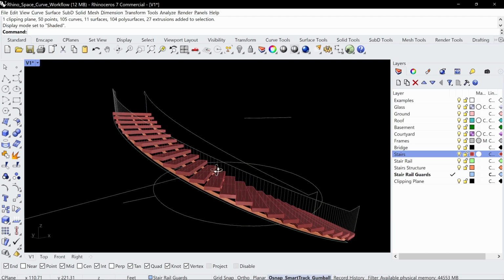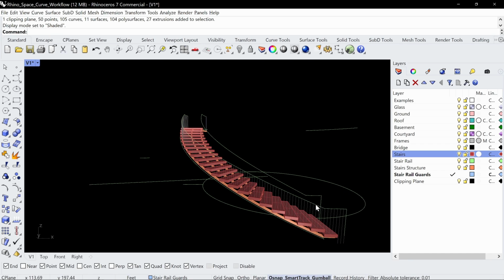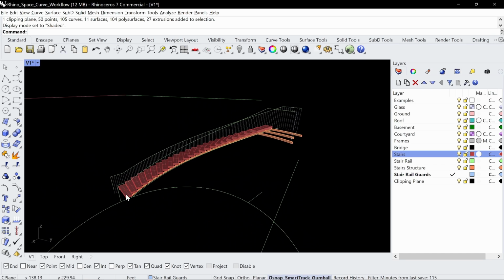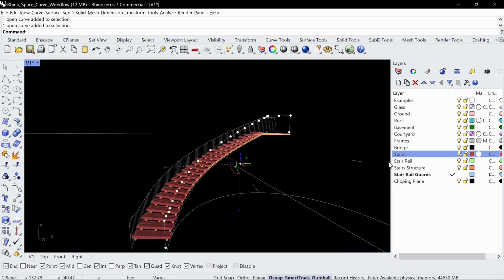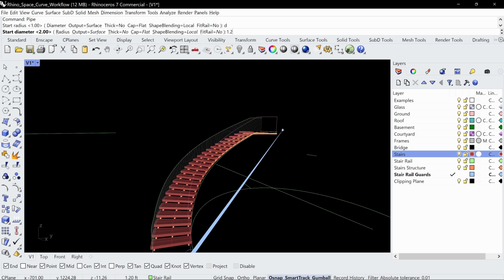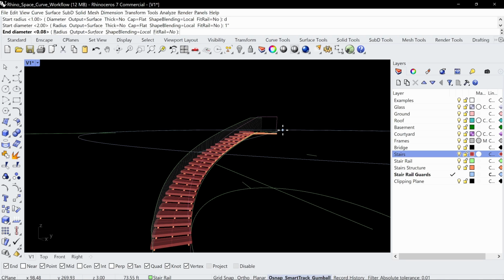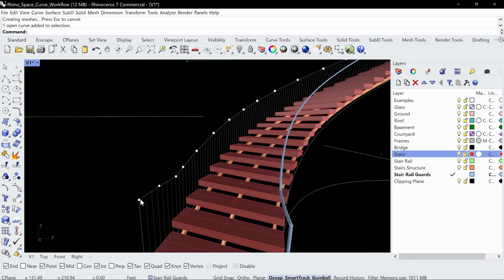So what I want to do is go ahead and pipe this as a rail. So let me click on, let's do this, join this, join this. So stair, yep. So let's just join that, pipe it, diameter. Let's do like 1.25. Well, that's actually big. The circumference just needs to be around 1 1/4, 2 pi r. We'll just do 1 inch. Like that. That's a pipe right there. And then we'll pipe this one, join this one.